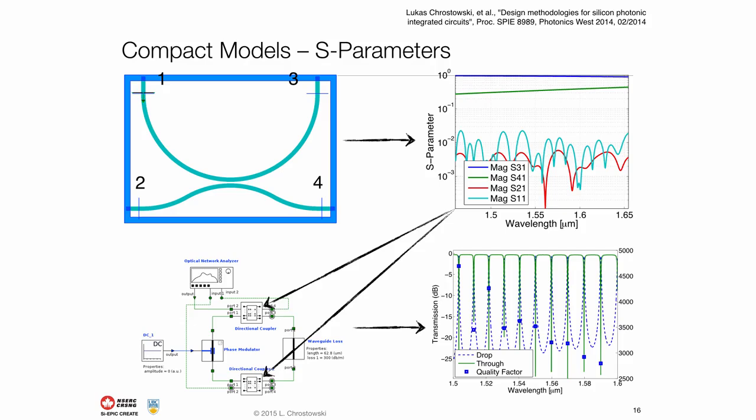Let's discuss the directional coupler that is used to make a ring resonator. This is a 4-port device, as illustrated. To make a ring resonator, we need a slight coupling from port 1 to port 4. We can simulate the S-parameters. The graph shows that there is a little bit of light coming from port 1 to port 4 of about a few percent. Most of the light from port 1 ends up in port 3. When you connect two of these couplers together to form a ring, most of the light is stuck inside the ring, hence it can resonate.